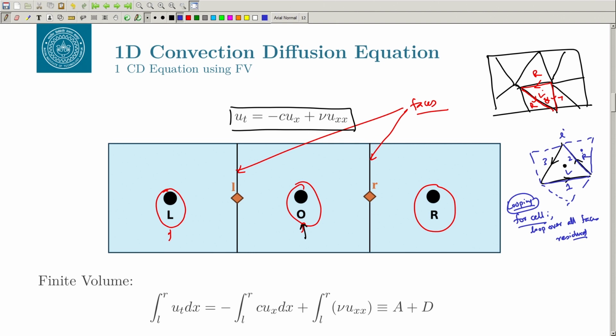So, basically you have to go towards each cell, find out the residual in each cell and sum it up, like we have been doing, like delta sigma f perpendicular j delta s j, right, and this you have to do in every single cell. So, the first approach is loop over cells, go through each cell and look for the faces and add that up. The other is loop over faces.